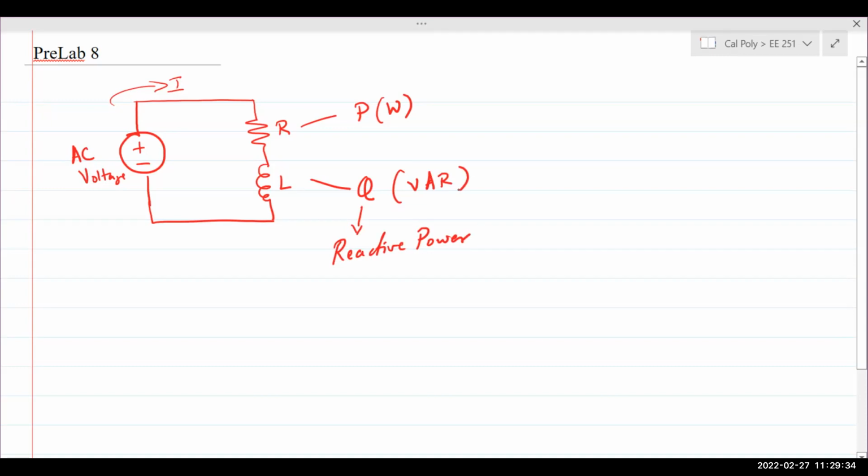Reactive power. Now, similar to the mathematical representation of reactance using the imaginary number J, we use the same concept to mathematically describe reactive power Q. So we say reactive power Q is imaginary, but it's not imaginary in real life. It has a physical basis, it has a physical presence, but the mathematical representation is imaginary, and hence it is referred to as imaginary. So do not be confused when you hear or read the words imaginary power. Reactive power is imaginary just means a mathematical representation.